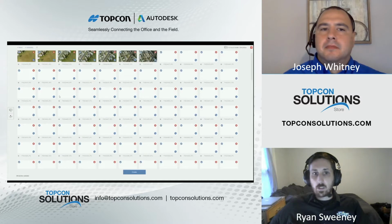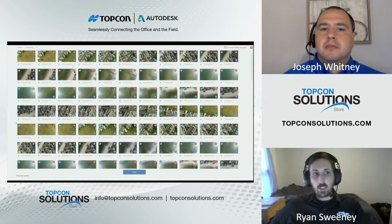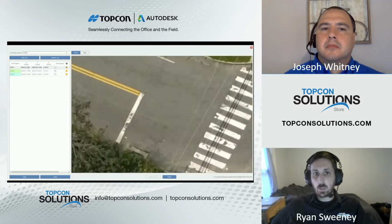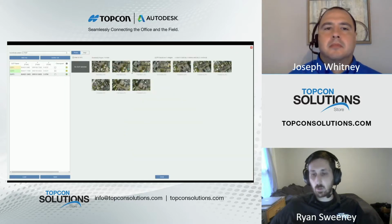So once those photos are opened inside of Recap Photo, we're going to come right down here and we're going to add some GCPs. So we imported them in, and we're going to go right into one of the photos. These are all geolocated, just like the images are. So GCP1 knows that it's near this group of photos right here. So we can just select into one and then zoom right on in, right to where I know I shot that GCP on that corner of that paint right there, and select OK.